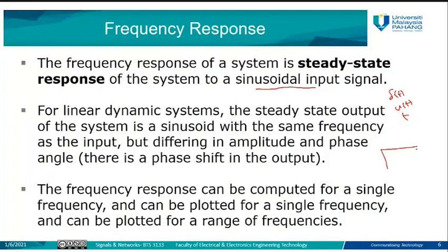So we have the transfer function here, which is G(s), for example, and we have the input to this system, like u(t). We said we have the output of the system. This is the input, we mentioned it as R(s). The output is C(s), and we said G(s) equals C(s) over R(s). So based on the value of the input signal, the value of the output will change, because the output C(s) is equal to R(s), which is the input, times G(s).